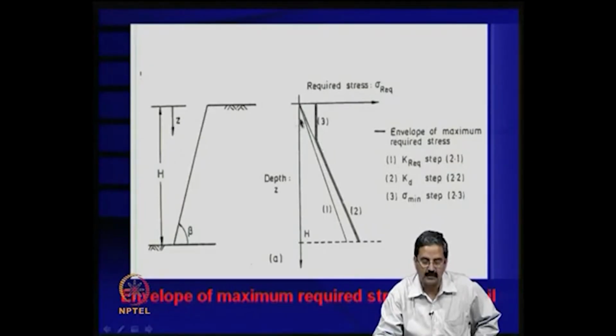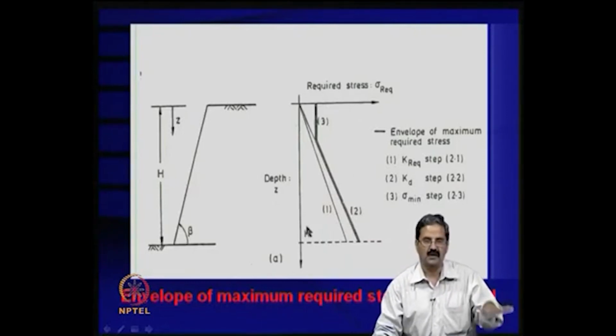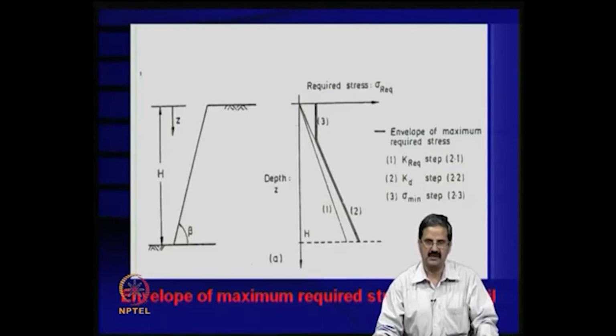Then at the top, you are trying to do the compaction, in every layer we do the compaction. But what happens is that the compaction stresses will be much higher; see, the overburden pressure is very high. During the process of compaction, we will have some sort of pre-stress induced into the system.